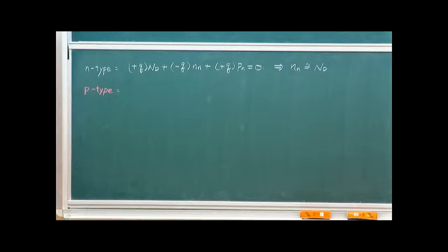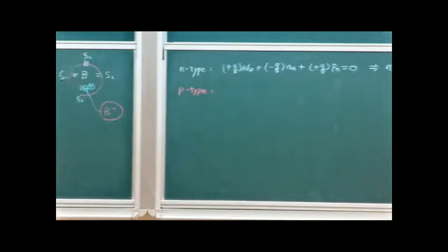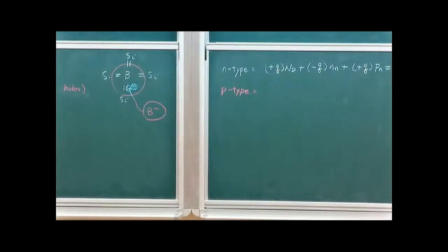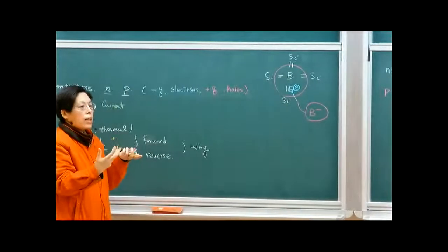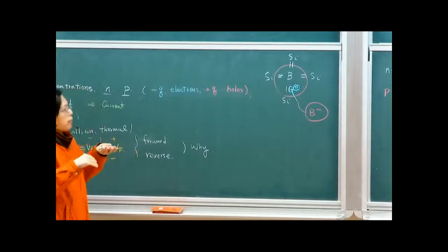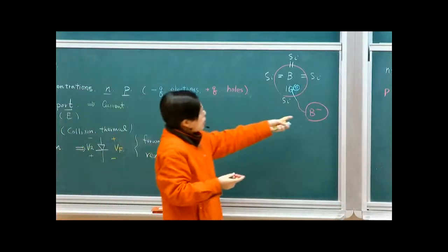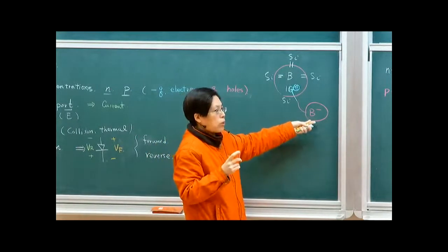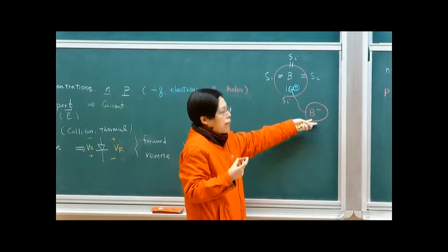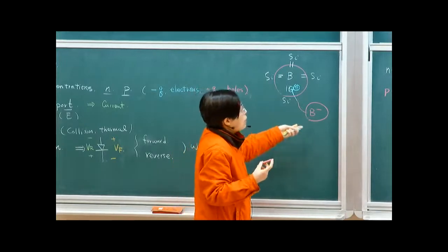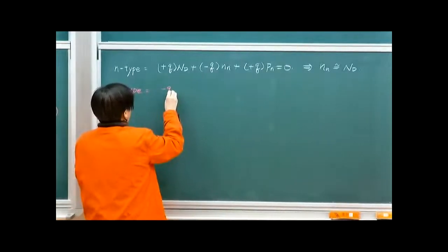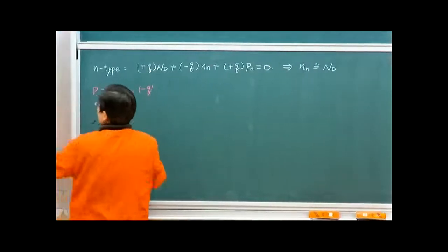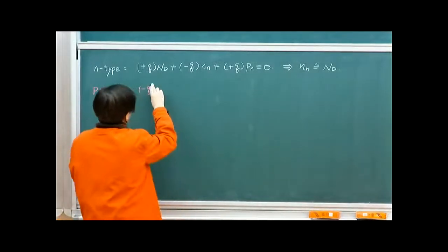It will be B minus. It's like chlorine and salt, so it's like an ionized impurity. It's just not in liquid, it's in solid. So for p-type, let me write the same. You have to recognize that your acceptor dopants, when ionized, become negative charge. Remember this boron accepts an electron in its empty seat, and it becomes negative charge.